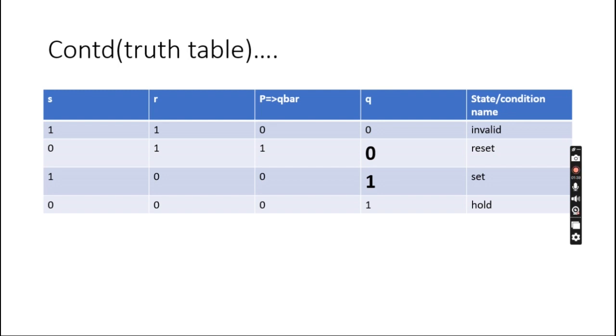So if we want to make it valid or useful, we should change any one input. Whenever the inputs are 0 0, even if we feed back the output many times, it will maintain the same output. We cannot go to a valid state from the invalid. So here in a NOR latch, if we keep this circuit at 1 1, when we apply input 1 1, it will be invalid. So whenever we want to make it useful, we have to change the input values.